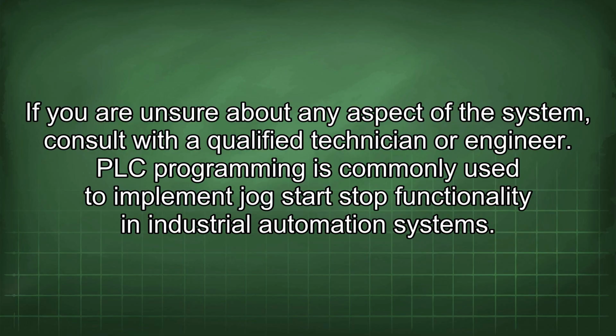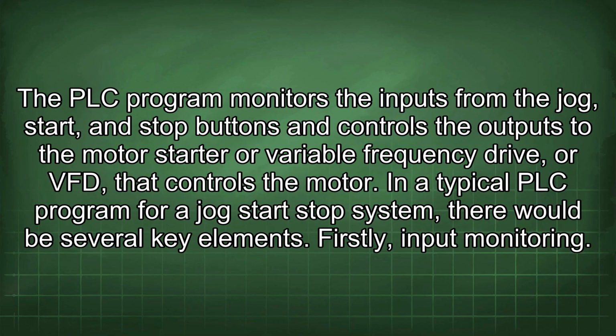PLC programming is commonly used to implement jog start-stop functionality in industrial automation systems. The PLC program monitors the inputs from the jog, start, and stop buttons and controls the outputs to the motor starter or variable frequency drive, or VFD, that controls the motor.